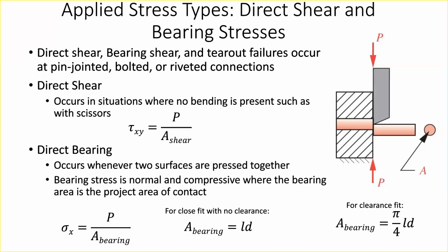Again, if you do this in FEA, you'd probably just end up upsizing this rod over and over and over until it can support this bending load. But if you understand the mechanism and form behind the loading going on in the part, then you don't have to go through that process. You can recognize much more efficient ways to load parts.